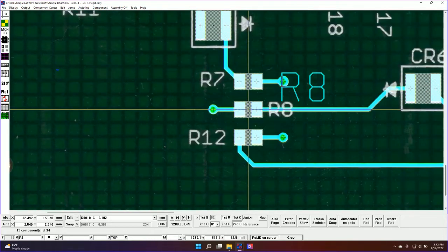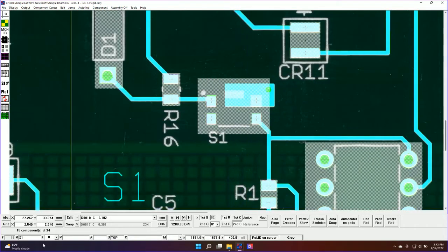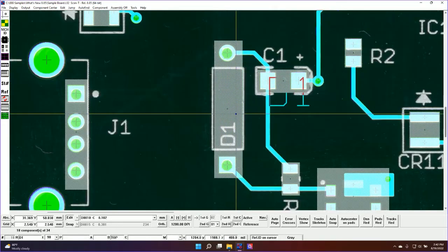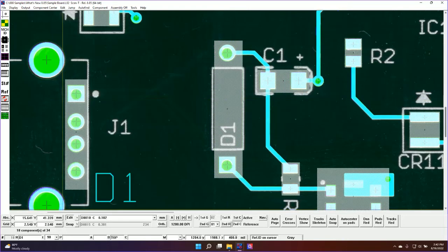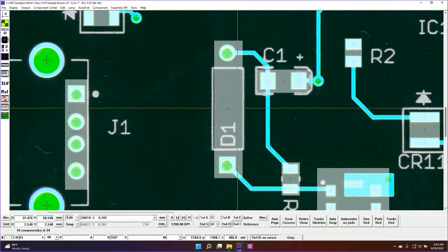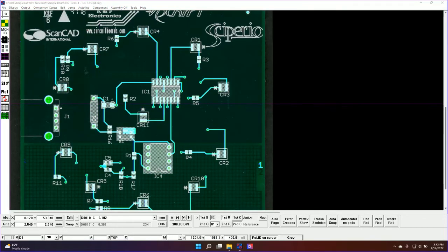And then when I get to one that changes, right, the rotation or a different one, I could check theta here, make sure that's right. And then when I get to one that changes, okay, now we're into 90s. And so I know the next several are 90s, and I need to make sure that these are correctly rotated. So that just makes assembly QC so much easier, again, especially when you're dealing with thousands of components. It's a lot easier to deal with.